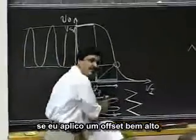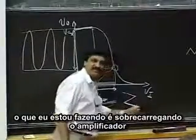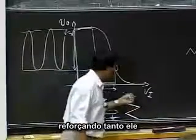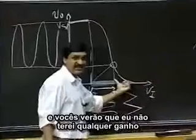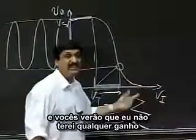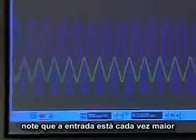If I apply a very high offset, what I'm doing is overdriving the amplifier, boosting it so high that the MOSFET is going to go into its triode region, and you're going to see that I won't have any gain. My output is going to shrink noticeably if I overdrive the input. So you'll notice the input going higher and higher.